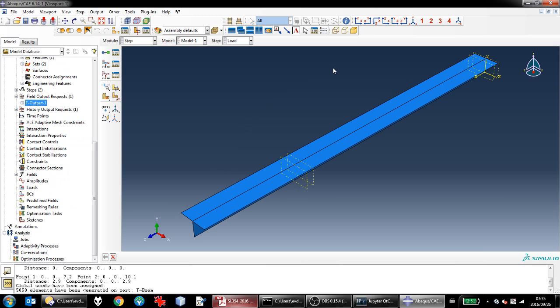So before I define that, I just want to point out something in terms of Abaqus's use of coordinate systems to give us output on shell element forces. I mentioned this briefly in the class, saying that if you go read the help file, you'll see that Abaqus says it chooses the shell element local axis based on the projection of the global x-axis onto the actual element. And if the x-axis is perpendicular to a surface, it'll actually default to the z-axis.